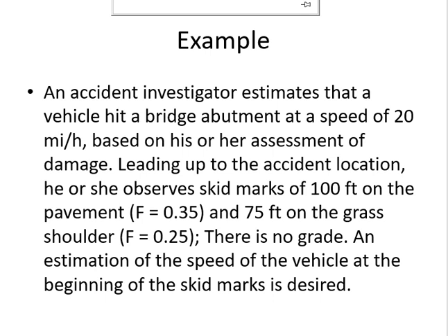Okay, and the same characteristics will apply to any other road user because all of them are obviously human beings, right? In vehicles, we said there are 4 important characteristics: deceleration, which is also called braking; acceleration; low speed turn; and high speed turn. For low speed turn, we have tables to design the curve because the external forces are negligible. For high speed turns, we have the equation to calculate the radius, and we have to satisfy the equation.